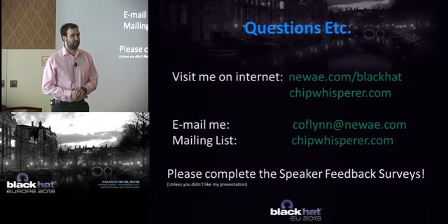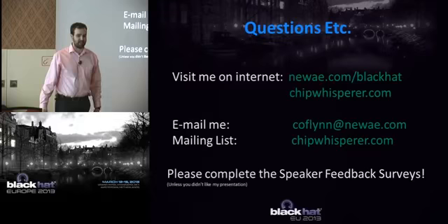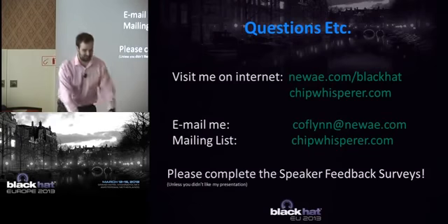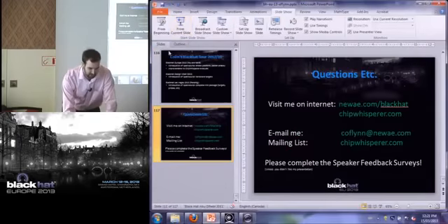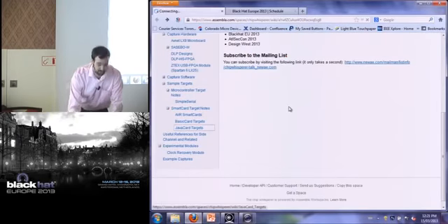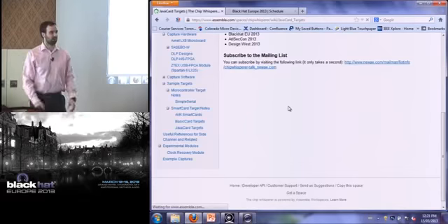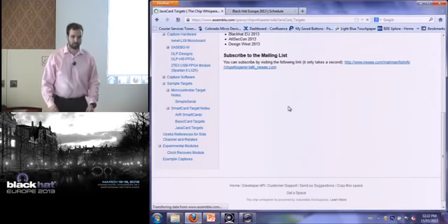Some of them are harder to get, though. Even the small 3-pin devices need an NDA signed to get the development kit, so that's not going to be useful. There are a number of Java cards you can buy. These are real smart card targets, but they do have some support for asymmetric crypto, and you can get started on them a lot easier.